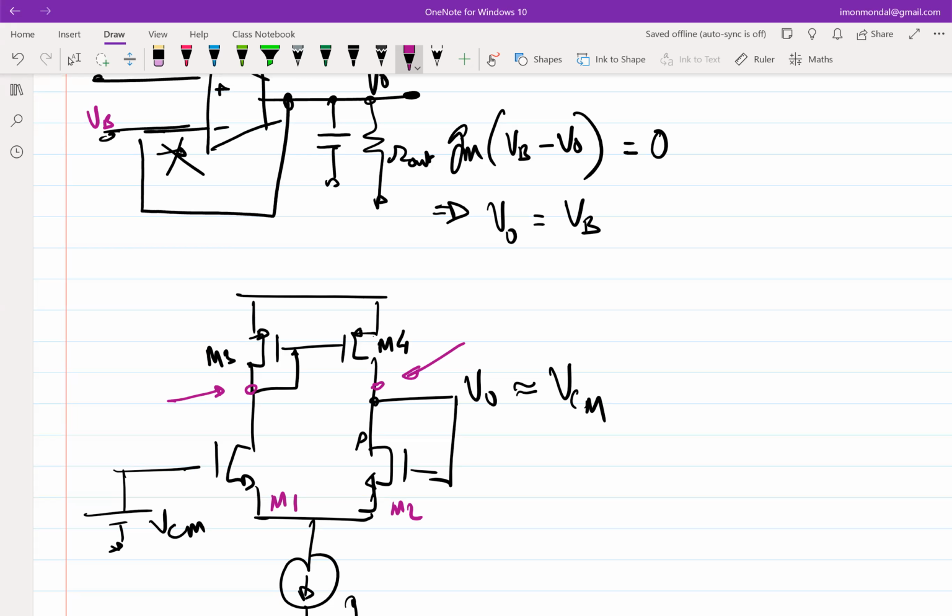Yeah, what? So let's say this voltage is VB4. So what is the maximum that this drain voltage of M4 can go to? VB4 plus the threshold voltage, right? Because you have a maxima constraint on the PMOS, right?